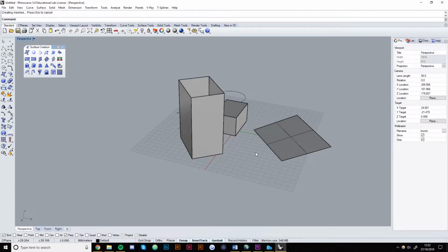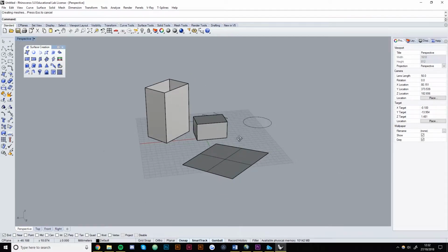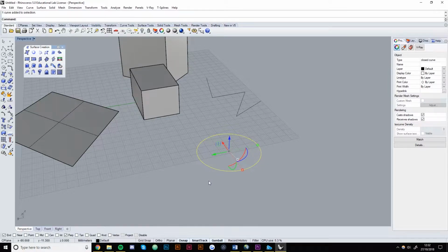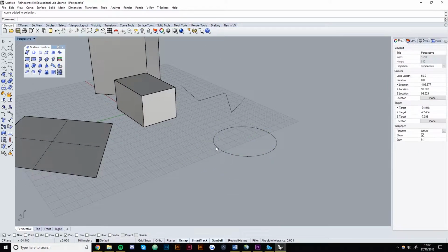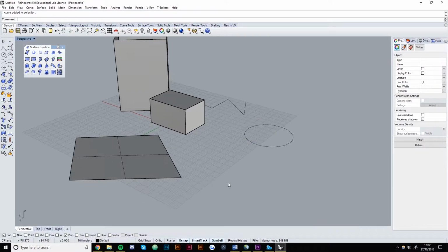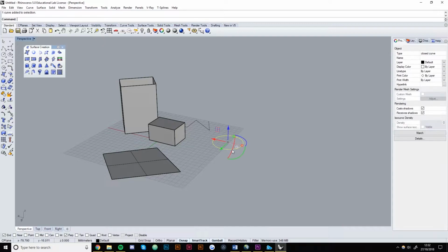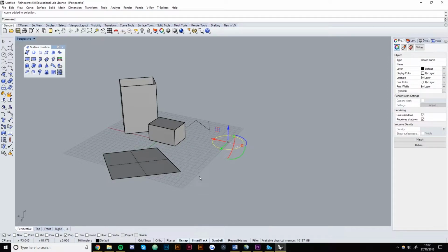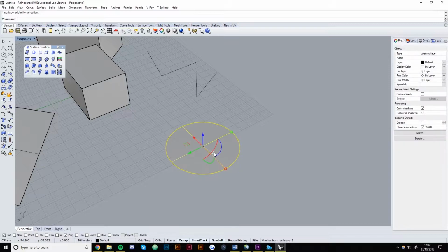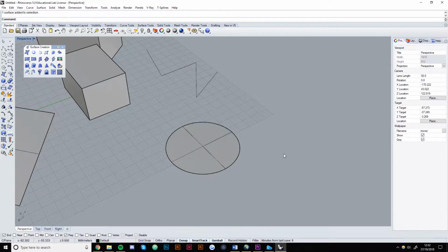There are 3 main types of objects in Rhino that we're going to be focusing on. We have these curves, which are empty. You'll notice that there's no automatic filling of the surface like you would in something like SketchUp. So this is only a curve. We can then fill in this curve with a tool like, for example, if I type in planar surface into the command line and hit enter, we now have this circle filled in,